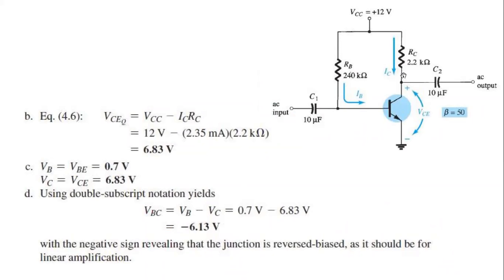The VCE, my student, if you see properly, this point is 12 volt. This 12 volt is divided into these two regions. So if we somehow find out this voltage and subtract from 12, the rest of the voltage equals the VC, isn't it? Because we all know that the KVL says the summation of drop voltage equals the total input voltage. The 12 volt is given here.